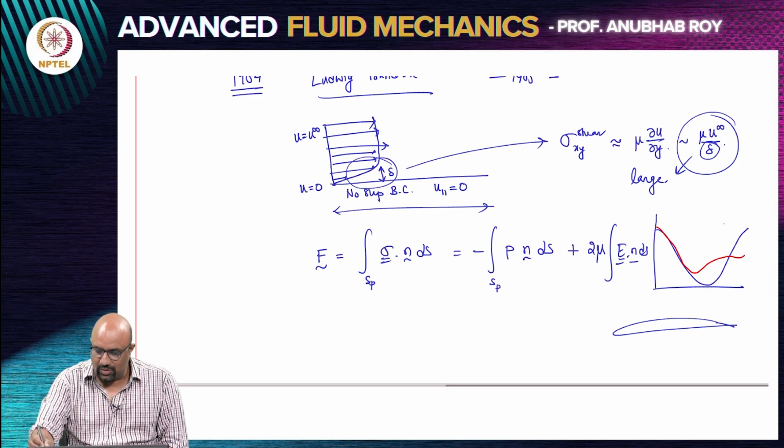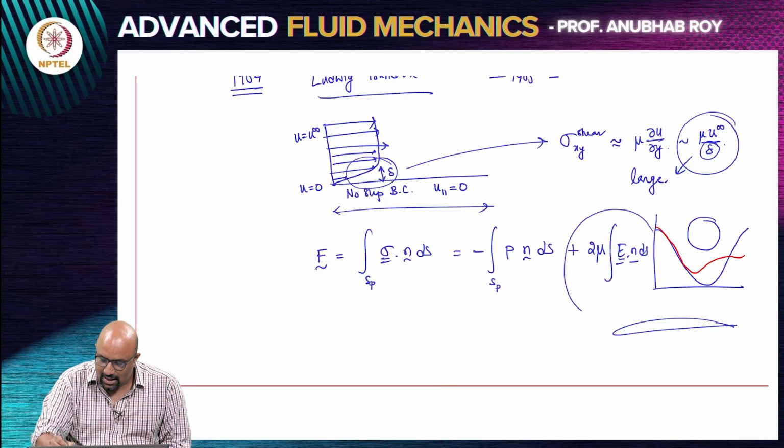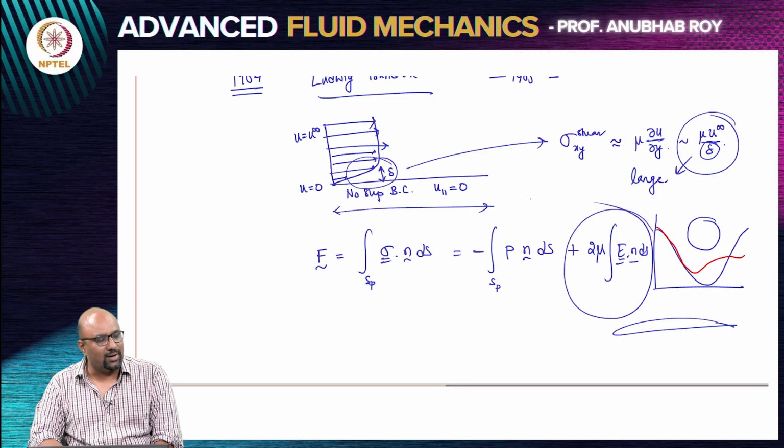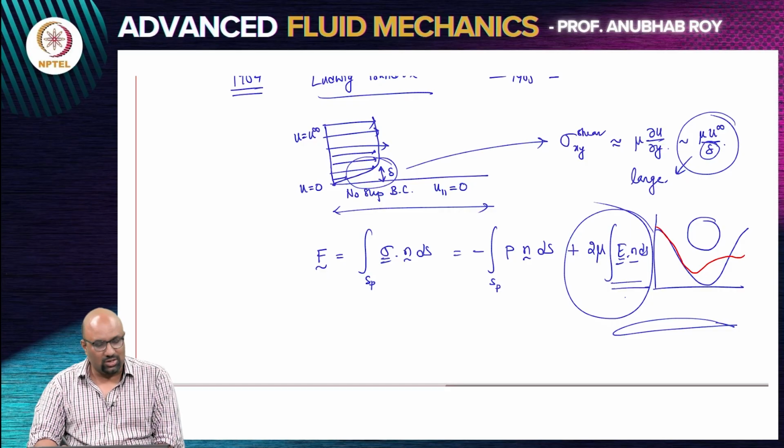Yes, for objects which are a bit bluff, there is a motivation of thinking in terms of pressure also, but the primary motivation for doing all of this is that there is a contribution to your force calculation that would come from your shear stress. You will need to integrate this quantity. We got a measure of what the shear stress is, and you will need to integrate this particular quantity over the surface of the object.